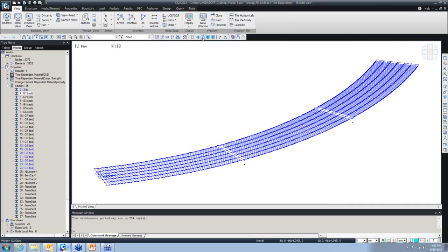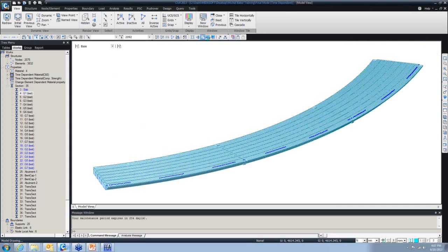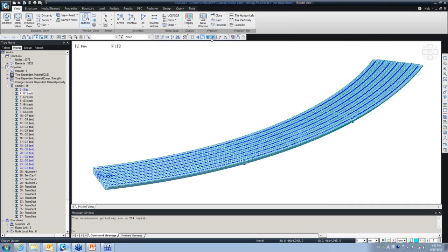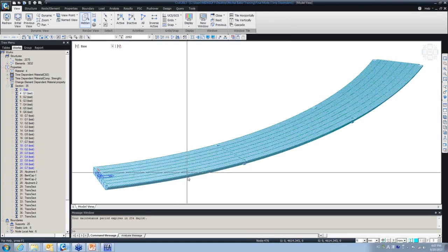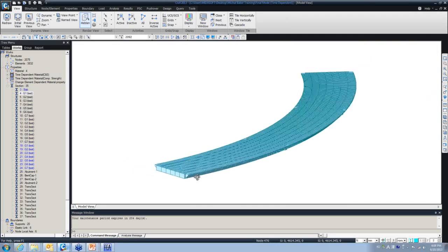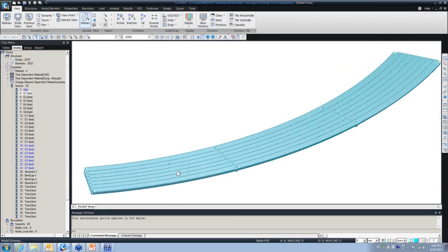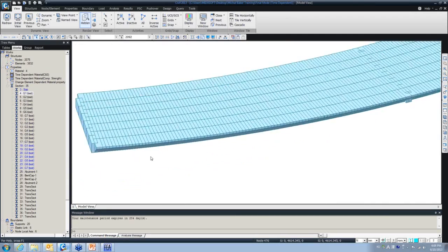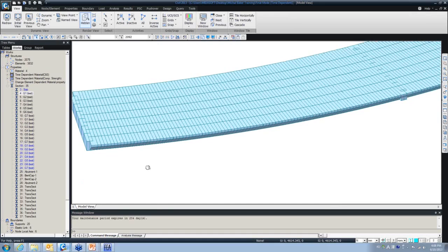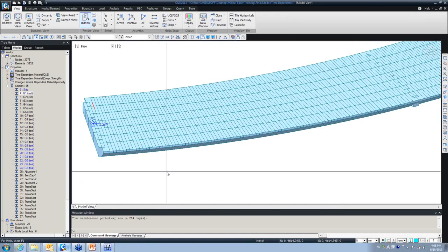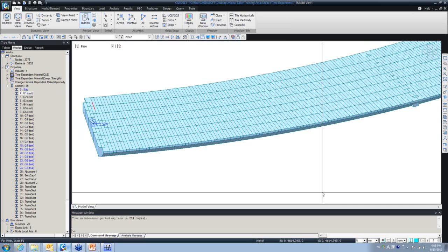So to answer that better, Joe, when we're defining the transfer elements, we normally use the slab width of the section. What happens is that these elements, because they are perpendicular to the longitudinal direction, are not actually playing any role or adding any stiffness to the longitudinal direction's stiffness.